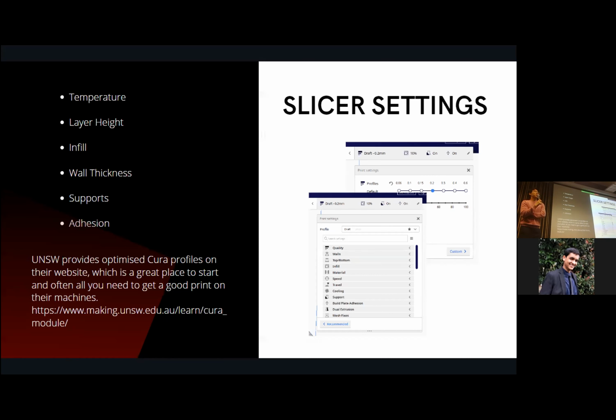It's pretty simple. Infill is how much material is on the inside. Because when we 3D print, right, we don't really want something that's exactly solid because it would take a lot of material. For the strength, for something to be strong, most of the strength of the object comes from the surface layer, and the inside has less effect on its strength. So usually we make it semi-hollow on the inside with some sort of infill pattern.